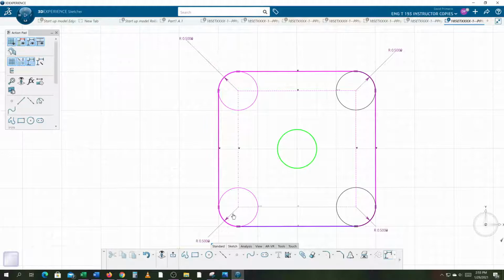So this toolpath is going to define the center line of where the cutter is going to go. So it's going to be removing material, going deep, and it's also going to be removing material along the sides. So as it comes around the corner, you'll have a radius. But here's the problem. When we talk about the engineering part has to maintain tangency, we mean that the toolpath really has to have tangency. So as the toolpath wraps around here, what's going to happen is on these corners it's going to chatter. Okay, you're going to mar the side of the radiuses.